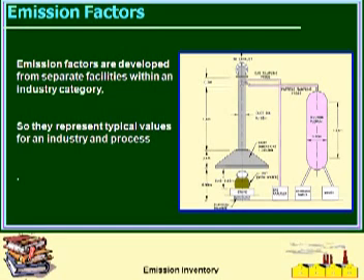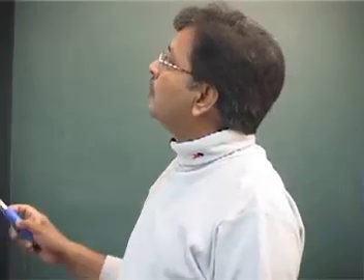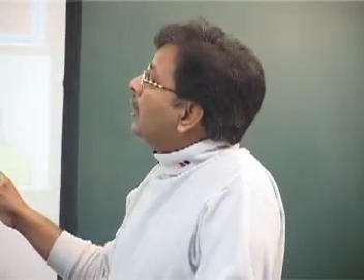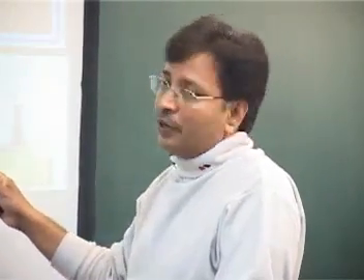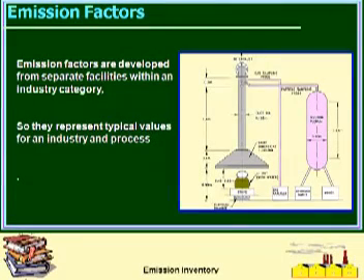See, we want the VOCs, which as soon as they come out, within a certain region, are going to condense into particulate form. If you take a sample too close to this, you will never capture it as a particle, because we know that in 2 seconds they will become particles. So whenever you are monitoring at high temperature, you should have some residence time so that you are capturing it after 2 seconds.